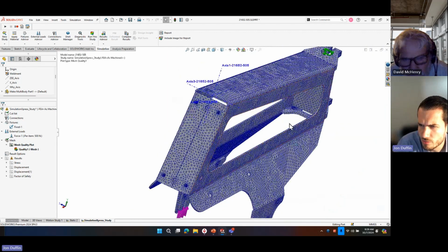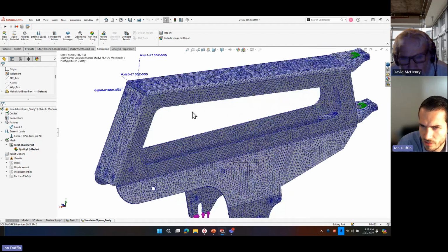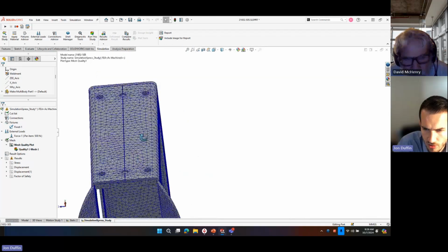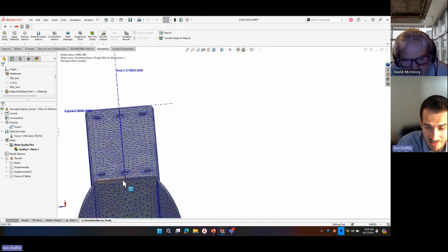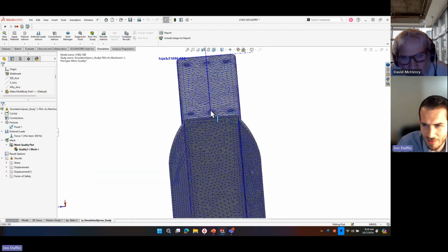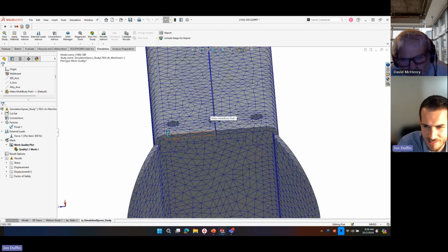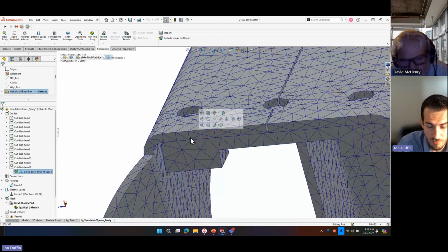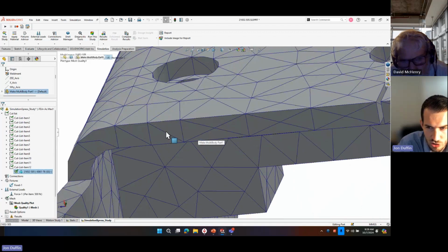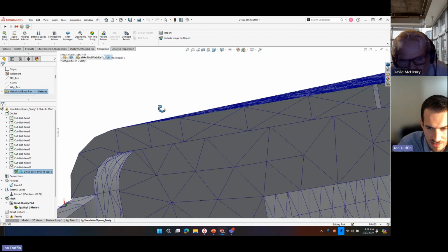Now the main question would be, because I had to go into a simulation directly in order to reduce this mesh density on here, even with that being said, I might even try to look at some high level results here to see the difference. Typically, your rule of thumb is that if you're modeling these as solid elements, you want at least two elements going through the thickness of these parts.